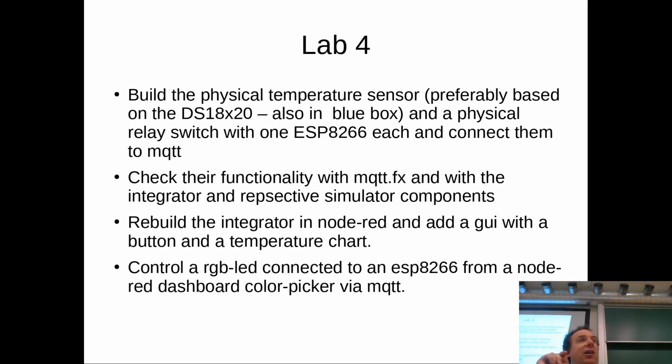And then there's a relay. There's a real relay switch in there, so you also want to connect it to a different ESP. Then you can check their functionality, so you can try out a little bit of testing directly with MQTT-FX, and then you can integrate it with your integrator. I think the third task we might move to the next time, because I won't give you a demo for Node-RED yet, so let's move that to the next time.